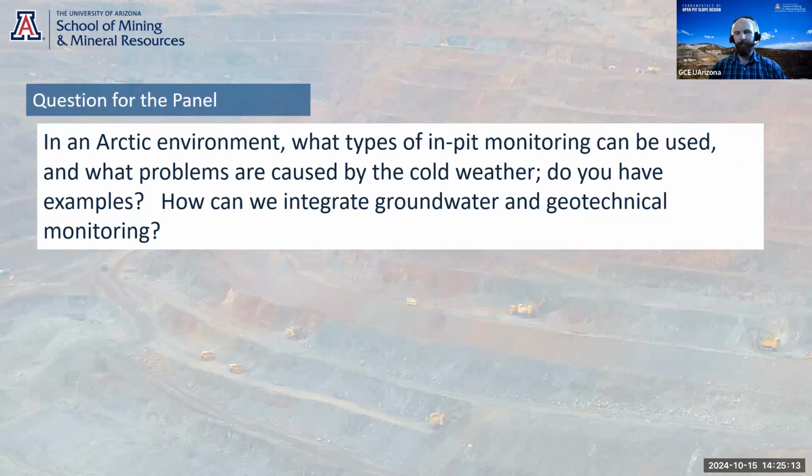I'll open this up to the panel. Again, I think vibrating wire piezometers are good in an Arctic environment, particularly the grouted in ones. The issue we used to have before the advent of vibrating wire piezometers was problems with putting monitoring wells through the permafrost zone because they freeze, and we used to use all kinds of fluids in the observation wells to keep them open.